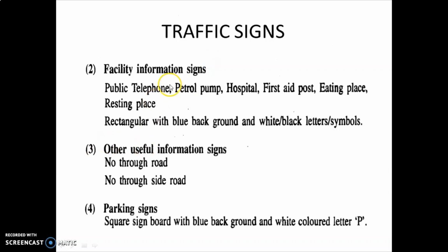Now traffic sign. Okay, so facilitatory informative signs: public telephone, petrol pump, hospital, first aid post, eating place, resting place, rectangular with blue background and white or black letter symbol. Other useful information signs: no through road, no through side road. Okay, parking sign, square signboard with blue background, white color letter P.